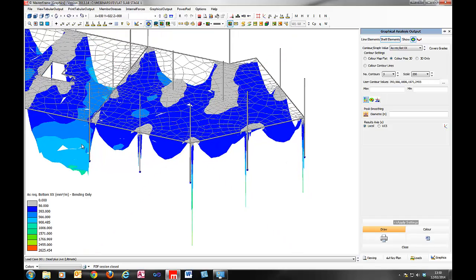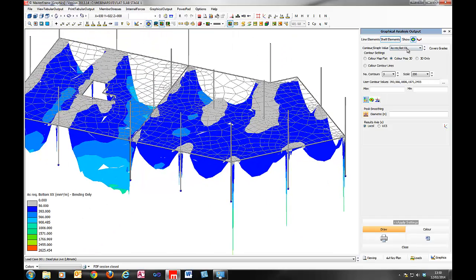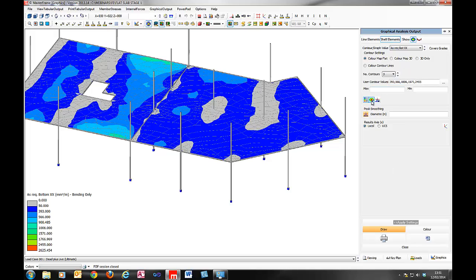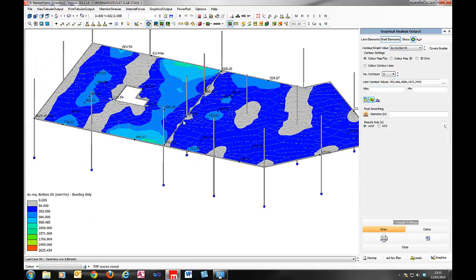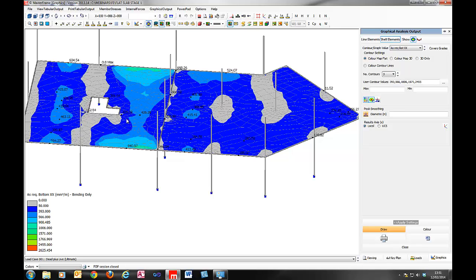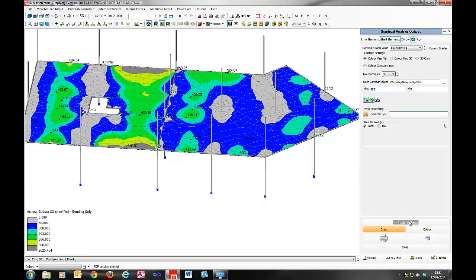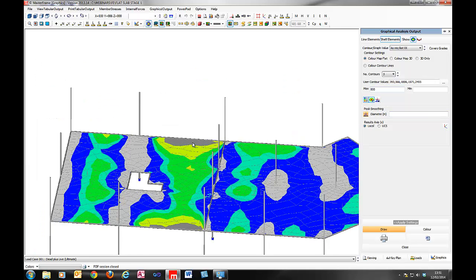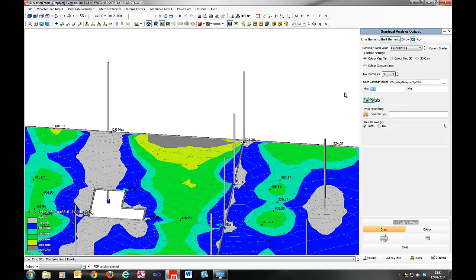So it might actually be quite useful to say, if I were to put that back in a flat view, let's annotate the surfaces, and realistically my maximum value of areas of reinforcement there is maybe 600 odd, so I can actually cap that. I can say the maximum value is 800 for instance, just giving myself a little bit of leeway, obviously. And now you can see anything above 800 is this grey value, so obviously there was another higher value at that location up there, so you might take that to 1000.